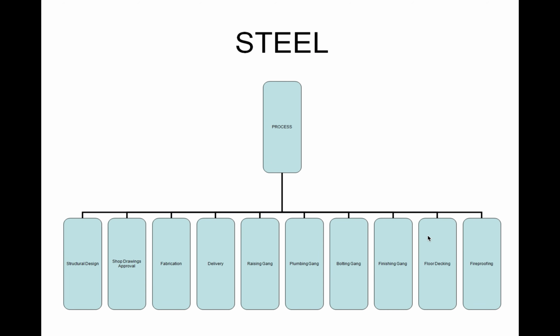All right, so there's a process for steel, and it's a pretty cut and dry one, very similar to any other material that you'll use in construction. There'll be a design. From those design drawings, a shop will provide exact details as to where the bolt holes are, where the connections are made, exact lengths, exact weights of each of the picks. All that will come on approved shop drawings so that you're able to develop your erection plans and to know how to put it together.